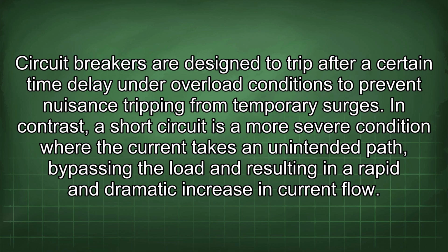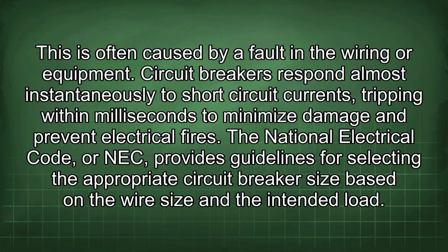In contrast, a short circuit is a more severe condition where the current takes an unintended path, bypassing the load and resulting in a rapid and dramatic increase in current flow. This is often caused by a fault in the wiring or equipment. Circuit breakers respond almost instantaneously to short circuit currents, tripping within milliseconds to minimize damage and prevent electrical fires.